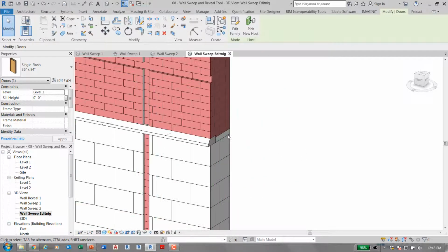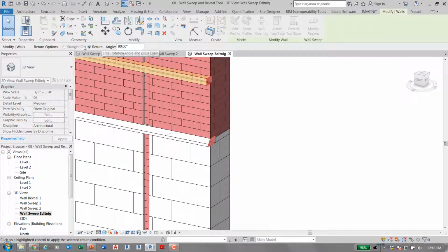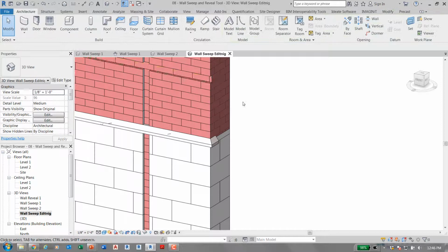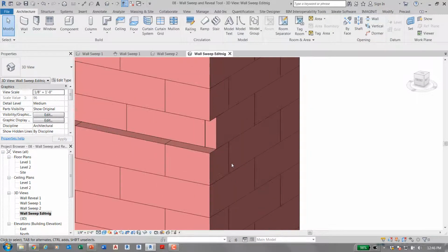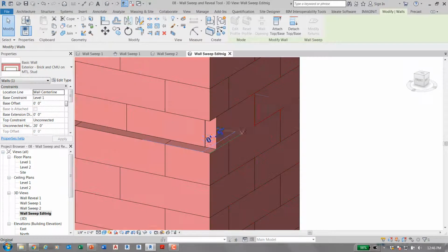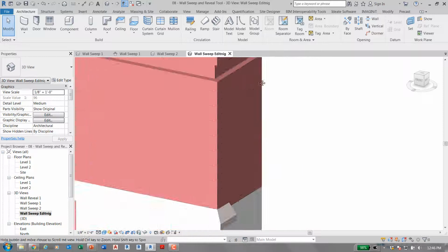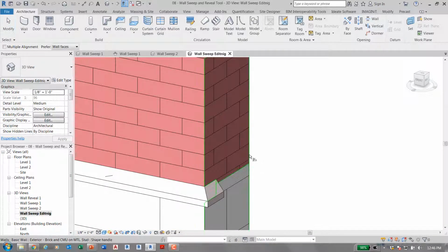All right, so what I want to do is pick my wall, modify the returns, and I just modify return. It's at 90, so these are my options here. I'm going to go and say, let's turn that corner, and let's turn that corner. Escape. A little closer here. When I pick on the wall, now I have two grip boxes. This one allows me to pull and cut. Okay, or I would use the align tool to that face.